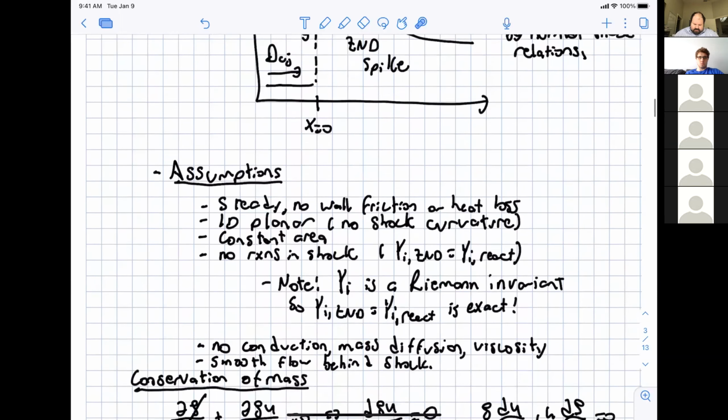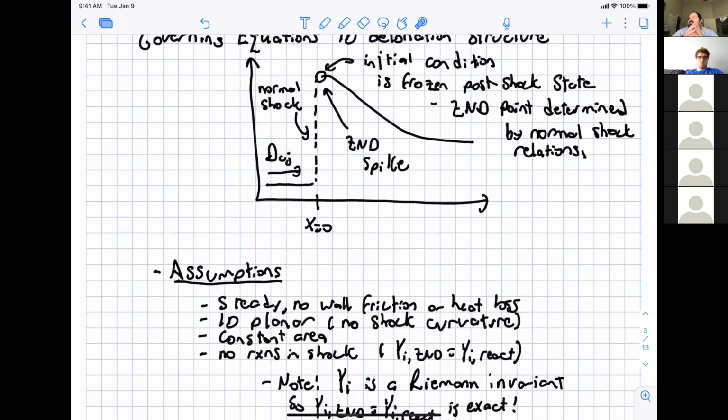I just have a quick question. The assumption of no wall friction, how accurate is that in terms of the development of a boundary layer? Obviously, this is moving at a really high speed. There is actually, in one of the references that I said are freely available, a discussion of that effect. It's actually fairly interesting. It's normally pretty small, just because, as you said, the detonation moves very fast, and also this reaction zone length here is typically very thin.